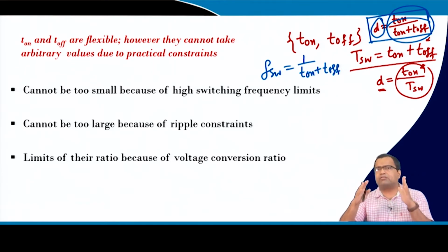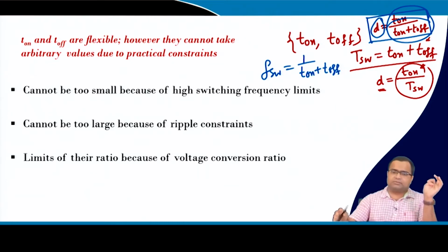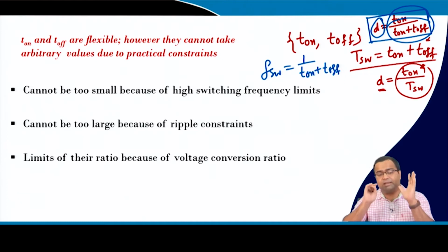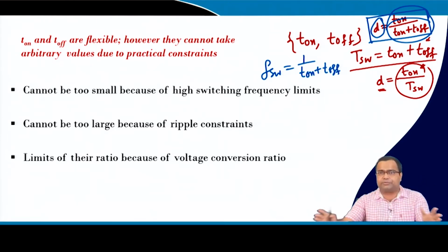converter, we cannot achieve in a practical boost converter a voltage gain of more than 3, it is very difficult, because again the gain will fall. Similarly for a buck converter step down, if we want to achieve a very high step down using a single buck converter with a low duty ratio, there are practical constraints and the losses can be very high, and that is why people try different architectures to extend the duty ratio either at low or high, whether it is a buck or boost, and there are different topologies.